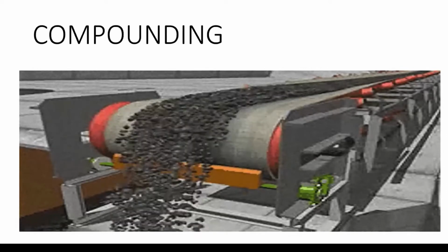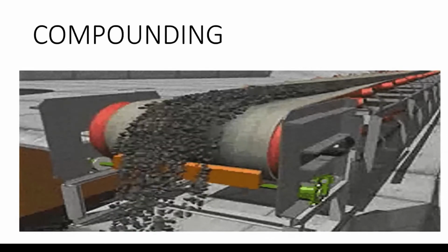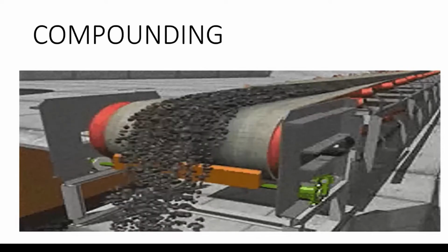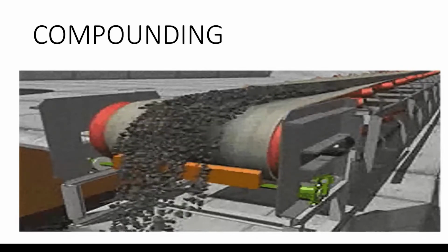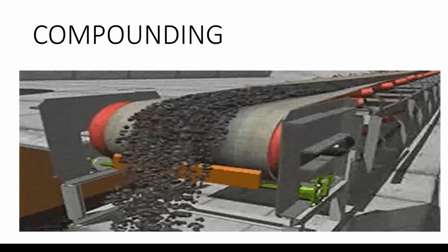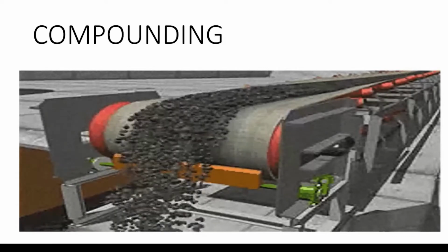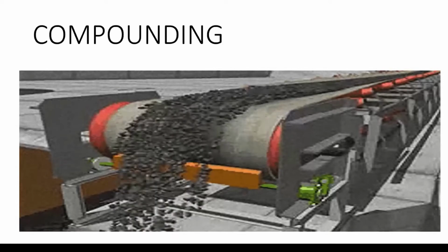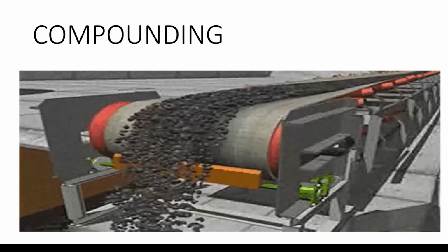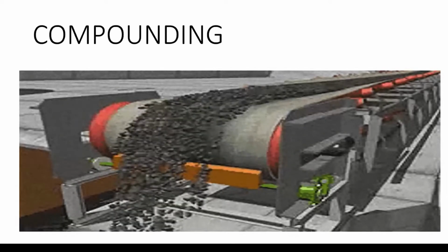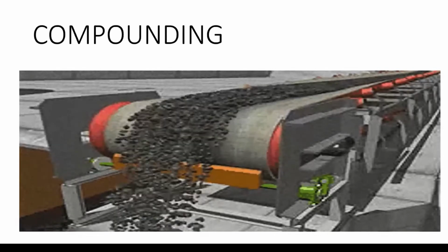The most commonly used reinforcing filler is carbon black. Derived from soot, carbon black increases rubber's tensile strength and resistance to abrasion and tearing. Carbon black also improves rubber's resistance to ultraviolet degradation. Most rubber products are black because of the carbon black filler.